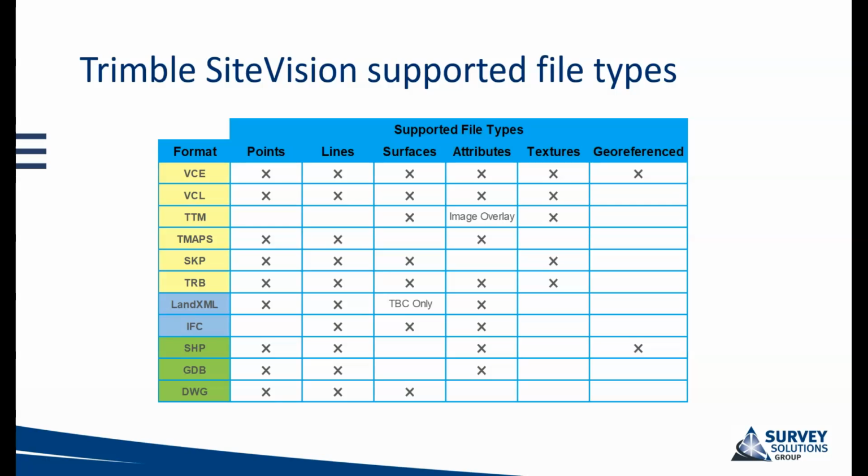These must be zipped before uploading to the Trimble Connect map viewer. This must contain your files with extensions SHP, SHX, DBF and PRJ. This format will already contain the coordinate system information, so you don't require a site calibration file. This is also true for Esri software files, geodatabase, GDB. Those are also supported and won't require a site calibration.